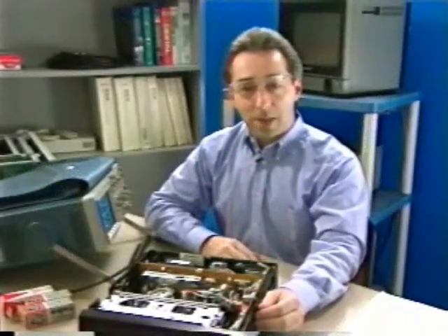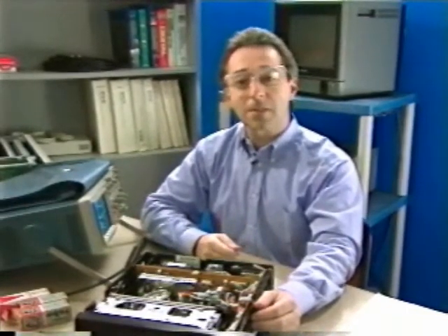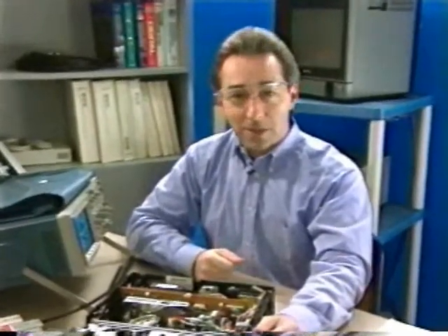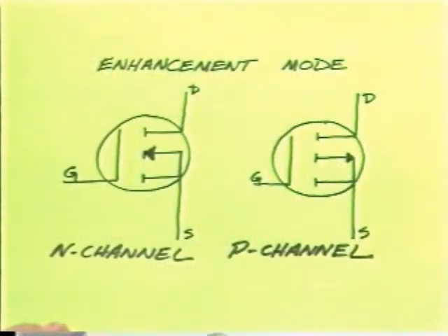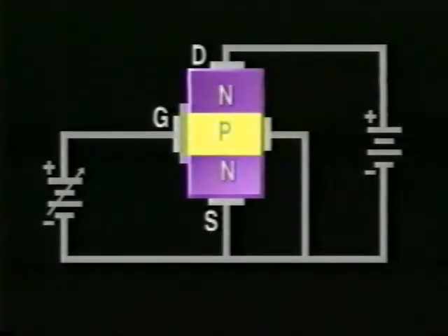While the depletion mode MOSFET is very useful in certain applications, the enhancement mode MOSFET is the device that has revolutionized the electronics industry, particularly in the area of digital electronics and computers. Let's take a look at its basic operating features. Once again, there are both N-channel and P-channel types. Here's a graphic representation of an N-channel enhancement mode MOSFET. The usual biasing voltages consist of the drain and gate voltage supplies. Notice that there's no current channel initially. Let's see how it works.